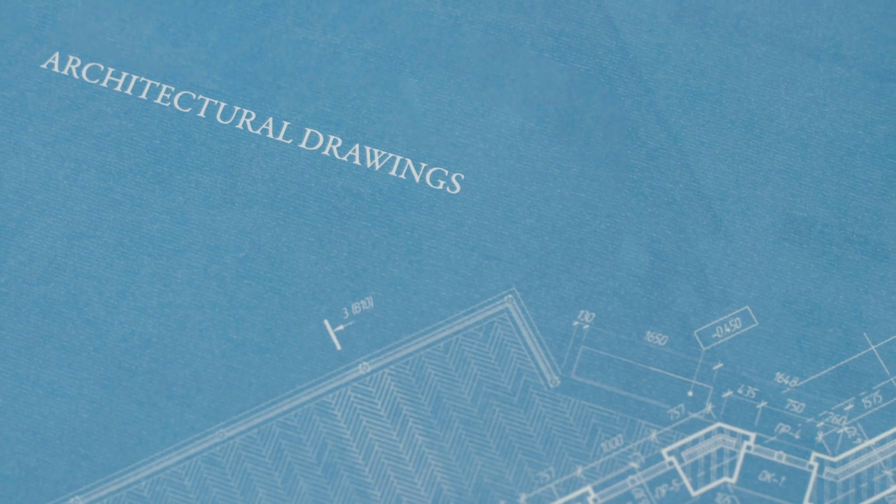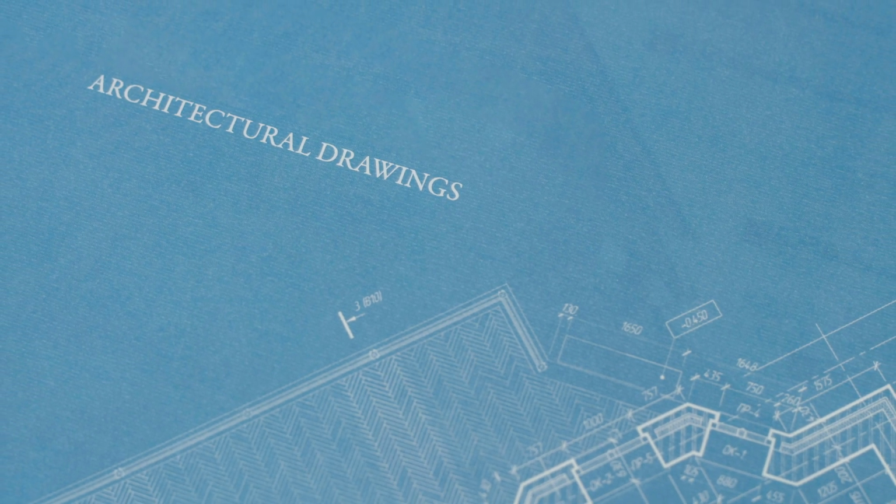So once we've had a back and forth with the clients just to make sure that these are indeed the ideas they had, we move to the next design phase, which is the scheme designs. The scheme designs are usually the blueprints that we issue for approval. So this has more information. They are the designs that usually have a little bit more dimensions, drawings, the materials, and these drawings, the scheme design drawings and approval drawings, are usually the same that we share with the other consultants, such as the engineers and the quantity surveyors. These engineers use these drawings to prepare their own set of drawings, and these are also used by the quantity surveyor to produce cost plans, bills of quantities that would help guide the budget.